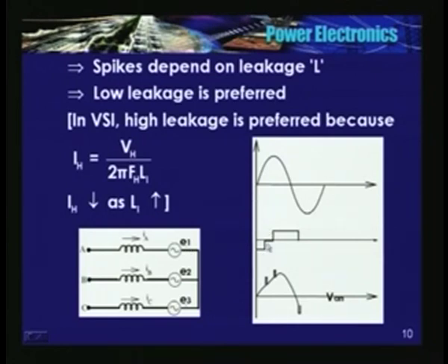Now, see, this is one of the phase current waveforms or line current waveforms, IA. Assume that it is IA. It was negative, became 0. For 60 degrees, it remained 0, and again a positive current. So, there is a positive L di by dt, again there is a positive L di by dt.